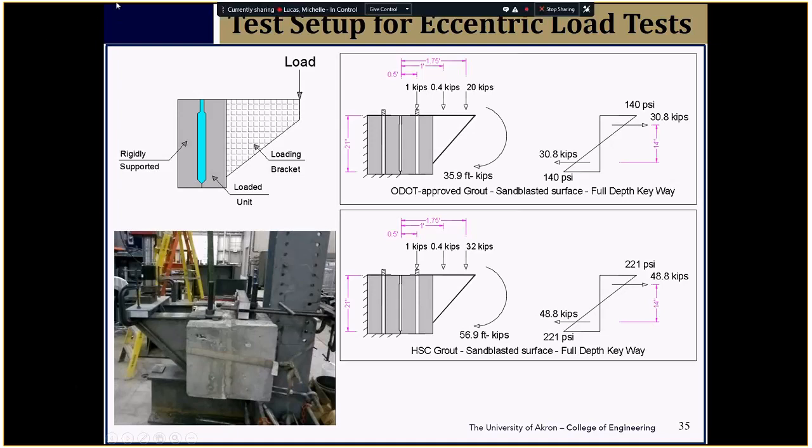That's what is challenging, and we did lots of analysis and got the combinations. The test setup looks something like this. We apply load here. You don't see a jack at the bottom, but we also apply another load from the bottom to make sure that the shear applied to the joint represents the actual stress condition in the bridge.